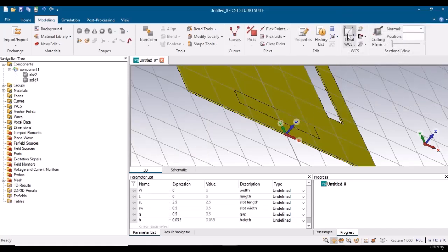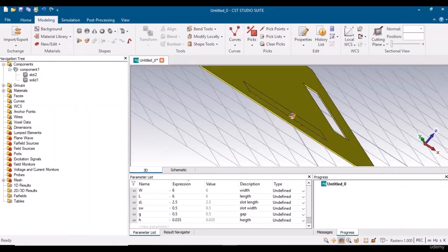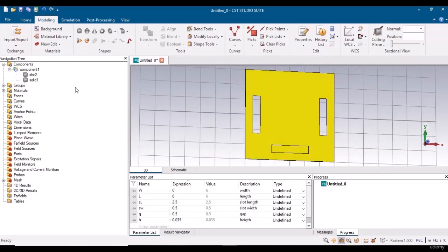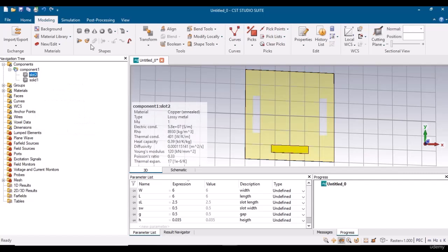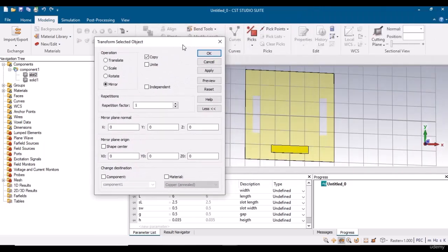Now click on this section, local W, to remove these coordinates. So now the coordinates are removed, and then rotate this section. So this is fine. Press space and then go to the solid 2 and click on the transform, mirror and copy. I need the copy version of this in the y-axis. So now make a view of it, and it is shifted in the y-axis.